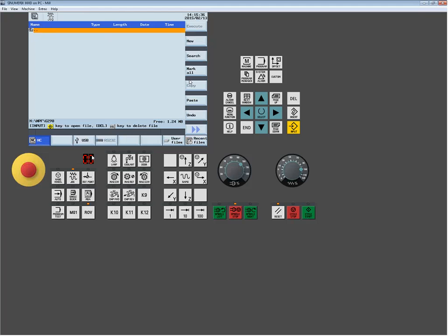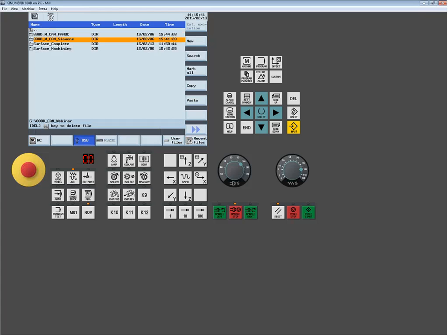When you get to some of the other controls, you can actually get a little more creative in your naming terminology. Once I've built a tool, I'm just going to assign some dummy offset to the length. Traditionally, this will get set by that tool length function we saw briefly earlier. When I want to set up my tools, it'll write to here. Then it asks me for the tool radius. Now, I said it was a 3/4 inch diameter.